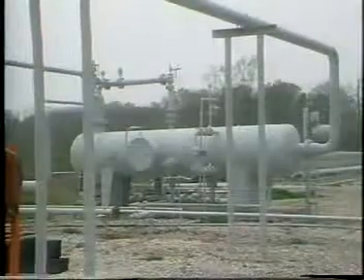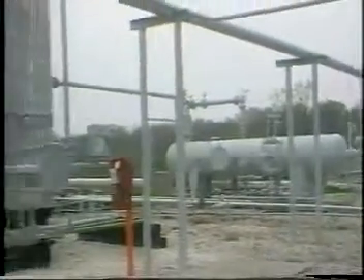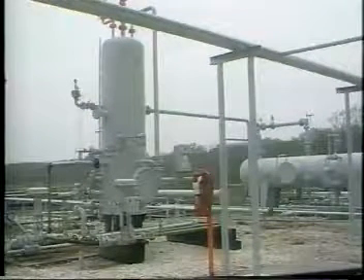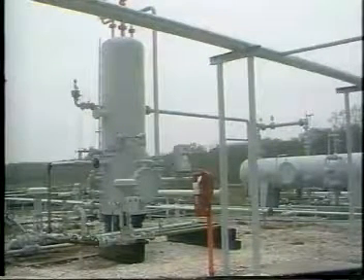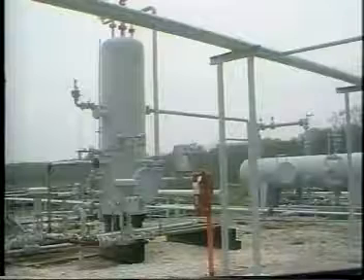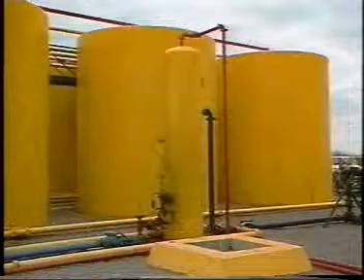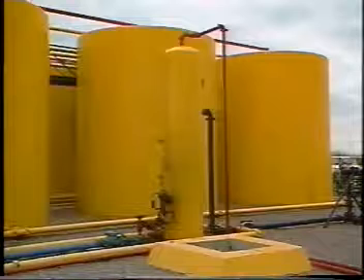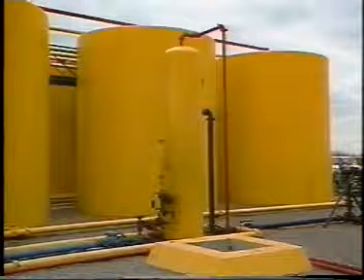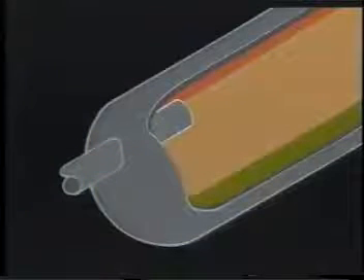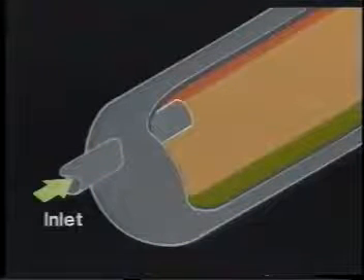Vertical vessels work most effectively in either low gas-oil ratio applications or in very high gas-oil ratio applications, such as compressor scrubbers, where only fluid mists are being removed from the gas. With this understanding of the general types of separators, let us look a little more closely at the common internal and external components of these separators. First, we shall consider inlet diverters.